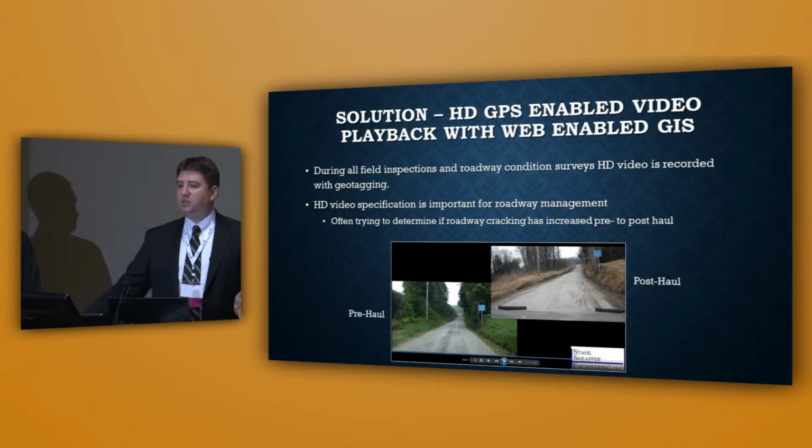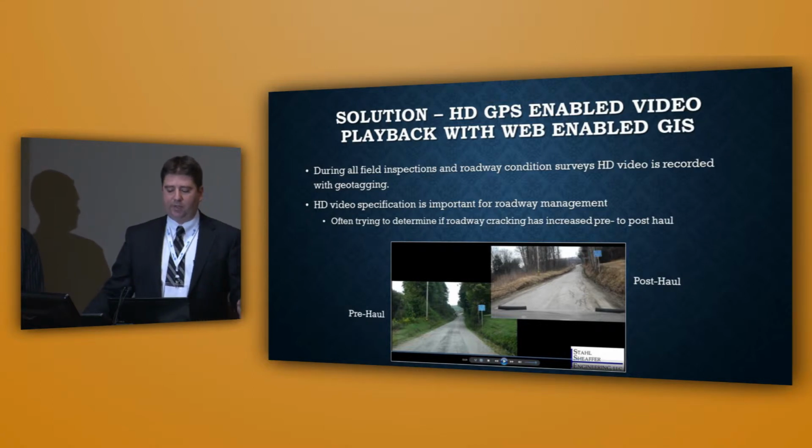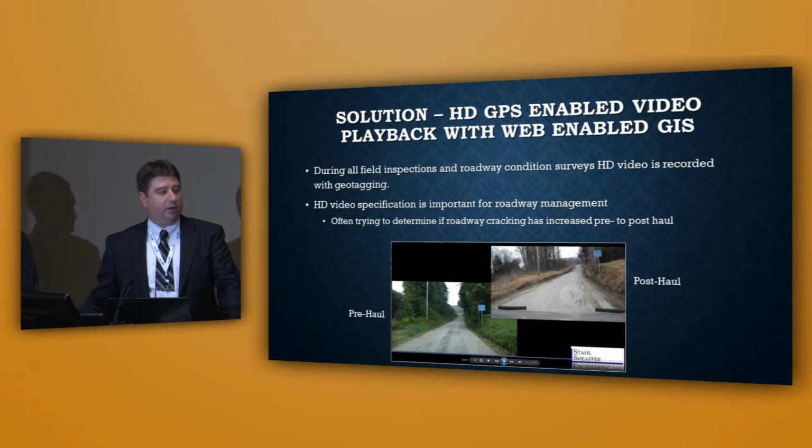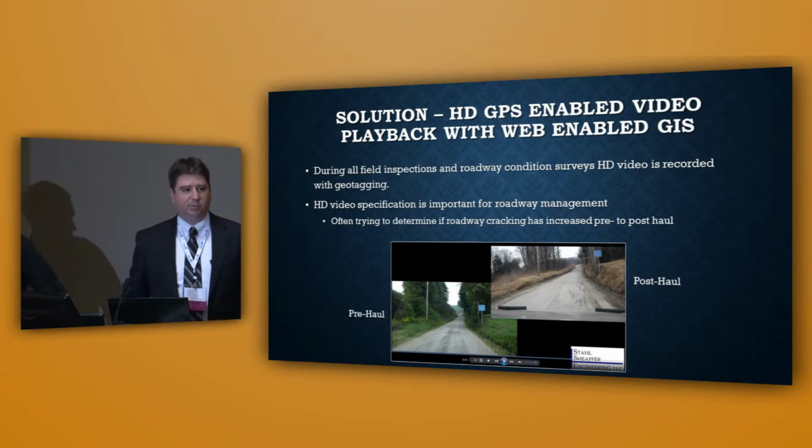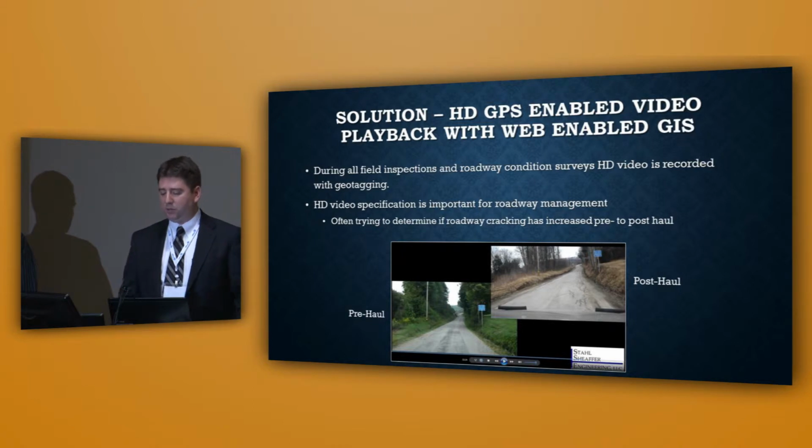During all of our field inspections and roadway condition surveys, high-definition video is recorded with geotagging. The high-definition video specification is important for the work that we're doing in roadway management because often we're trying to determine if things such as roadway cracking has increased from the pre-haul to the post-haul condition.